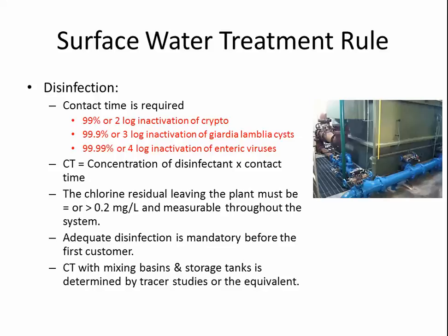Adequate disinfection is mandatory before the first customer, so you can't wait for your contact time to occur after you've been serving the water to your customers. So contact time with mixing basins and storage tanks is determined by tracer studies or the equivalent, and if you have questions on that or need help with that, please contact our engineering section.